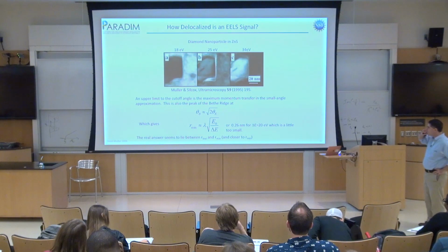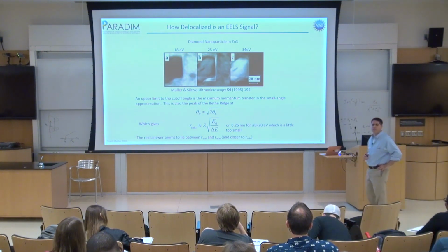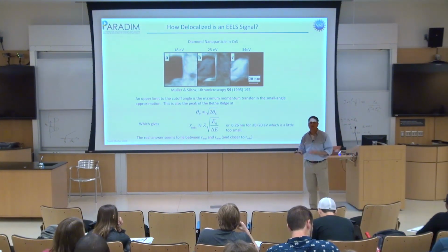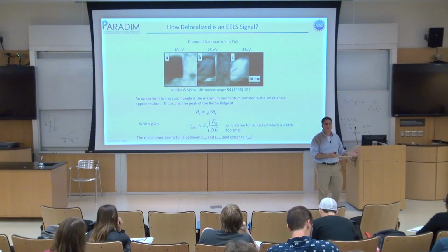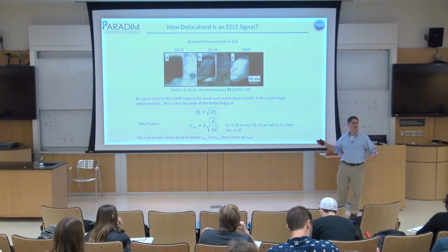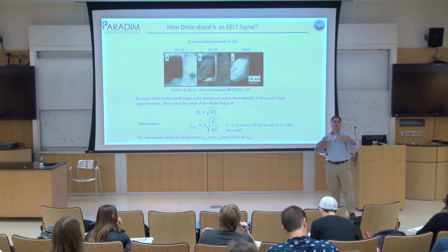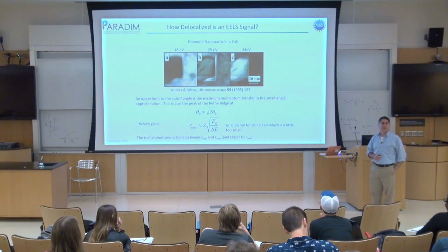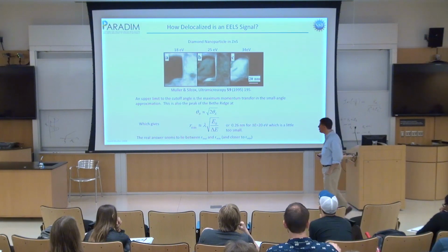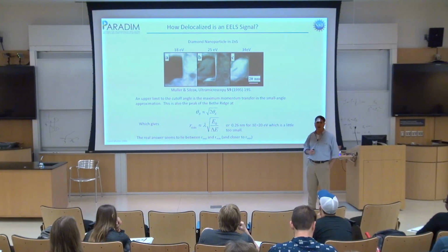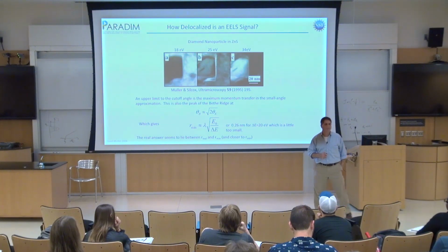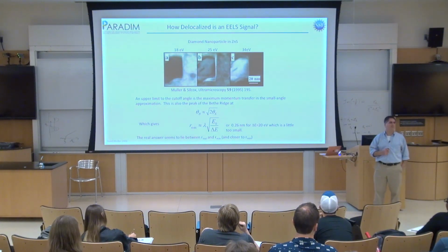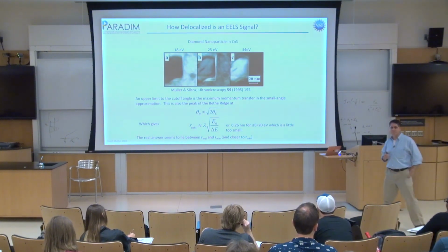Okay, so Lena talked about spatial resolution for core loss EELS. For core loss EELS, where things are a couple of hundred volts in energy, the spatial resolution went from a few angstroms to below 2 angstroms, and eventually at high enough energies below 1 angstrom. So all very nicely set up for atomic resolution imaging. The bad news for valence EELS is that's not going to happen. You're not going to get atomic resolution out of a plasmon spectrum unless you've made a very big mistake. And we can talk about what those artifacts are, and if you stick around for the workshop, I'm sure we'll talk about those artifacts again when people make those claims again.